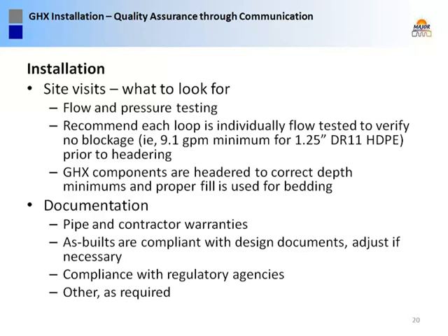The other thing I've seen, if you're out there observing it, and all of a sudden you get a slug of water coming out of the loop that's muddy and dirty, that goes back to quality control of the installation, that someone wasn't watching their pipe and they've got it contaminated. So that might give you some recourse to get them to do it right. So other things to look for, proper headering depth, that sort of thing.